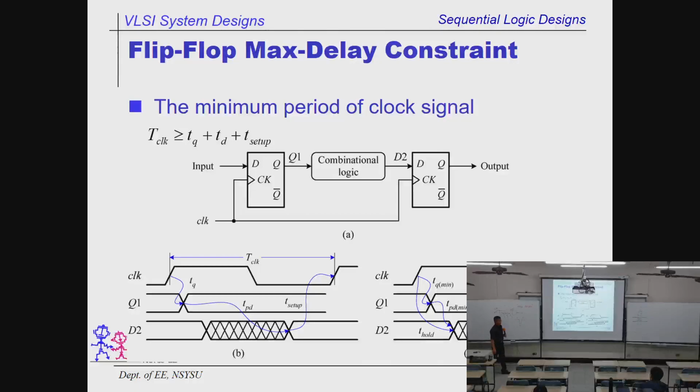Okay, then this is your circuit design in your final project. You have an adder, for example, or multiplier in between. Then as I said, you gotta have a lot of registers. Remember I said on Monday morning, you gotta have an array of flip-flops to synchronize all the operands you want to do the addition. Then you gotta have another array of registers to do the output generation. Both of them are driven by the same clock. All right? So this is the thing.